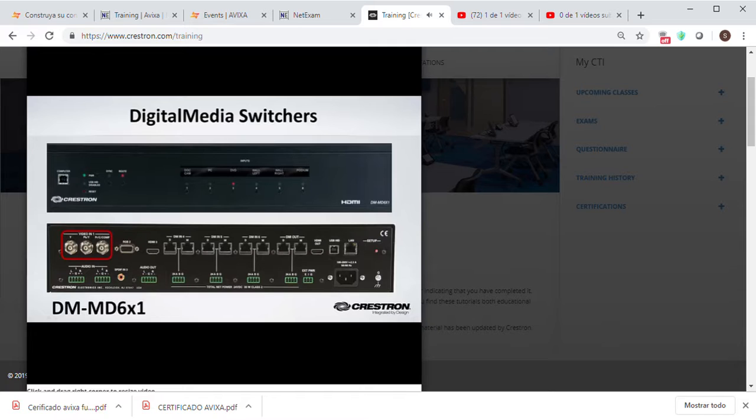Video input 1 is an analog input for either composite, S-video, or component video connection through the use of a BNC style connector. Video input 2 is an analog input for a PC connection through DB15 connections, but also is capable of accepting composite, S-video, or component video signals with the use of a breakout cable.